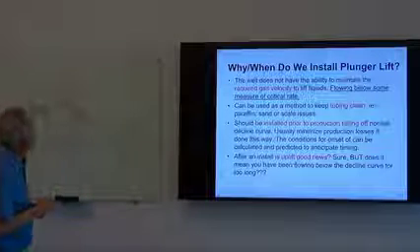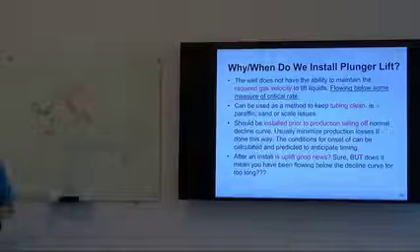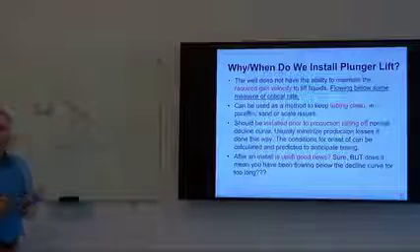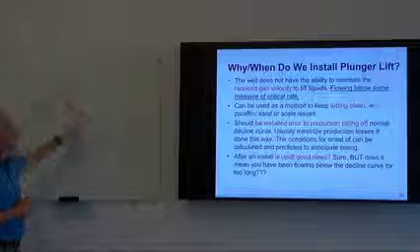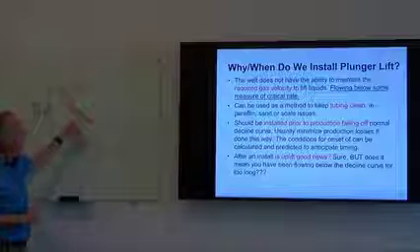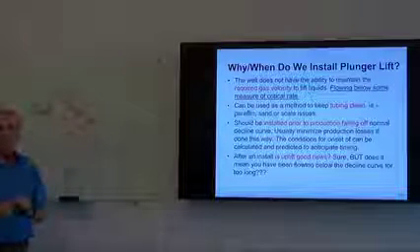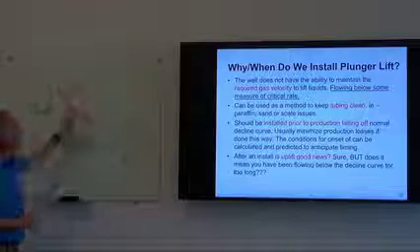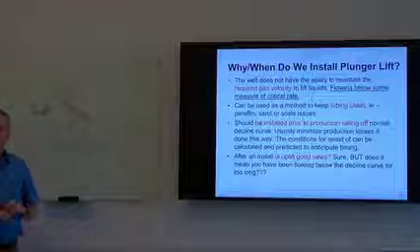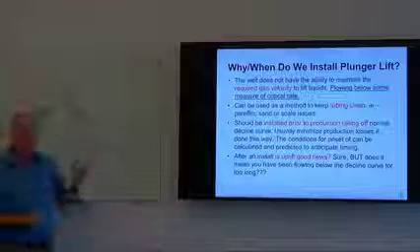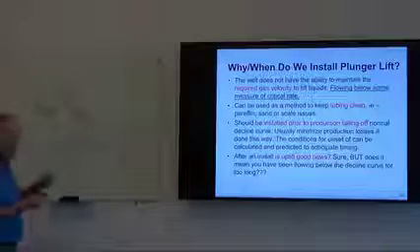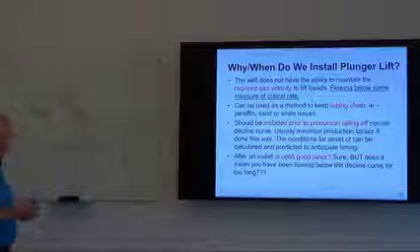So the idea of when to install plunger lift, and traditionally, if I think back over the years, was people waited for this situation to occur. And then at some point, it's, well, we have to fix this. Let's finally put our plunger lift system on and all is good. However, there are these cumulative losses over a long period of time that may or may not ever be recovered from this well. So timeliness of intervention is very, very important.